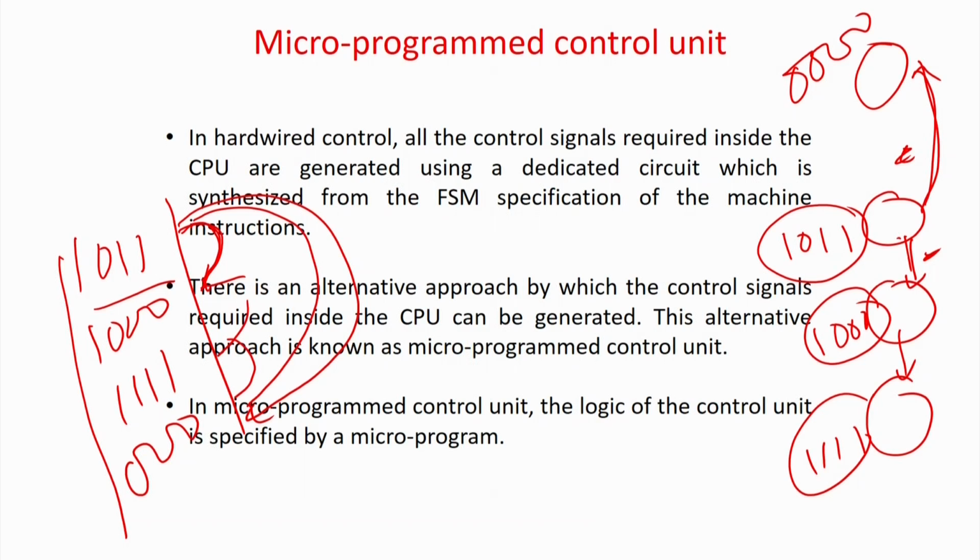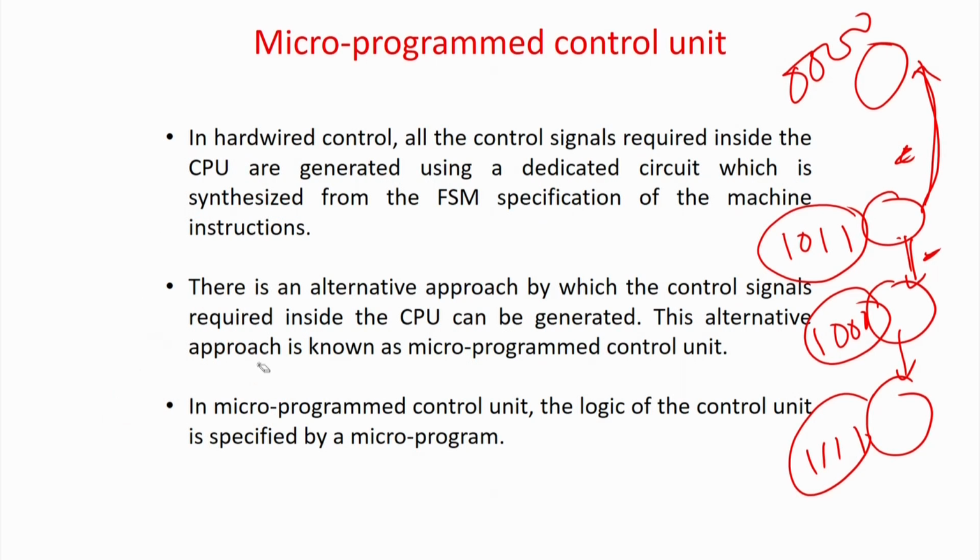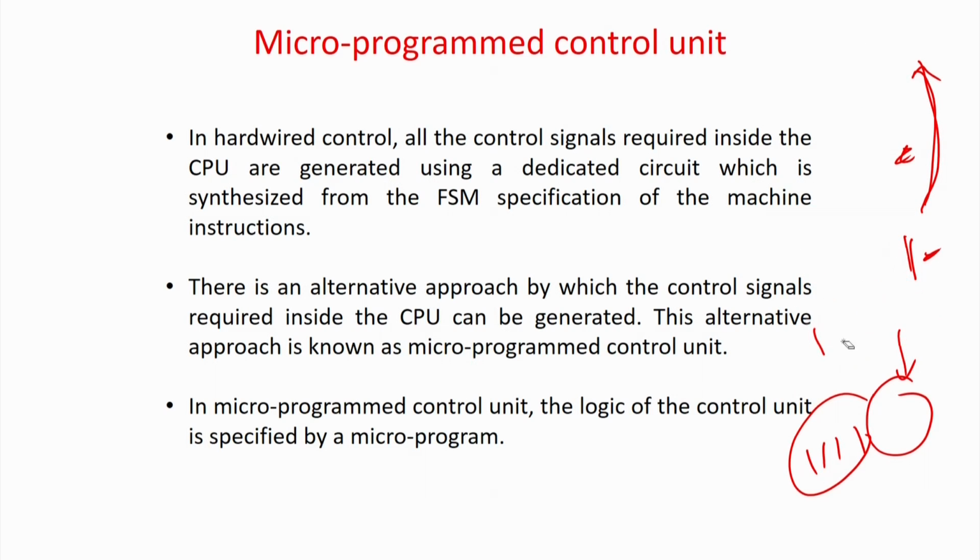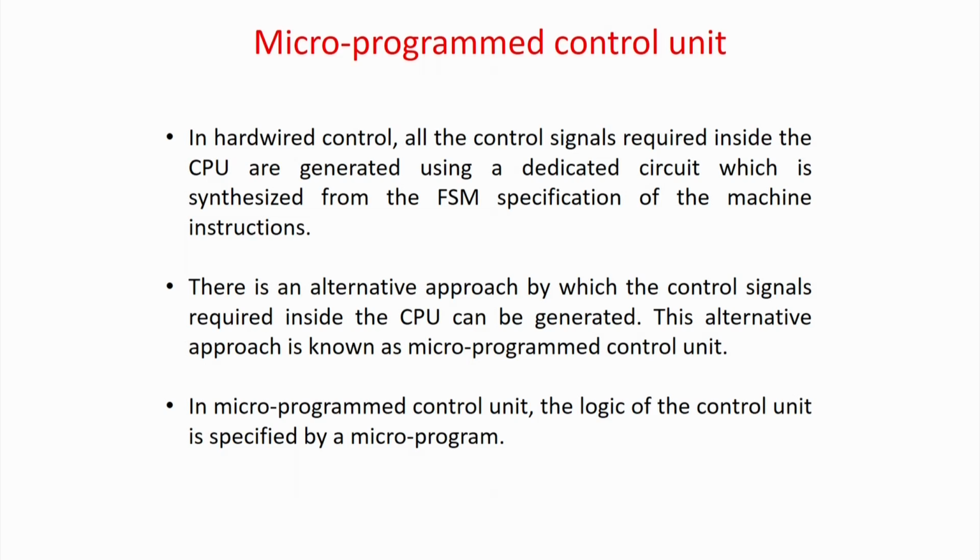But overall, the microprogram is very flexible, because you can easily change the code based on the requirements. But the sequencing is slightly tricky, which is more difficult in case of a microprogram. Jump instructions based on some condition check are slightly sophisticated compared to a finite state machine. So basically that is what a microprogram control unit is.